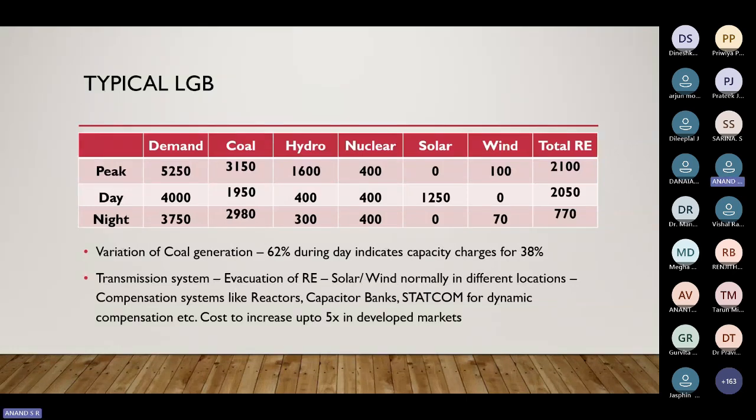Now to operate Lower Periyar or Neriamangalam or Chenkulam, we need to have water released from the Madhupetty reservoir, which is through the Pallivasal generating station. So Pallivasal generating station has to run almost around the clock, to ensure sufficient water availability in case of peak load.